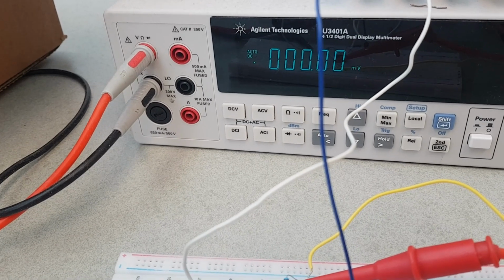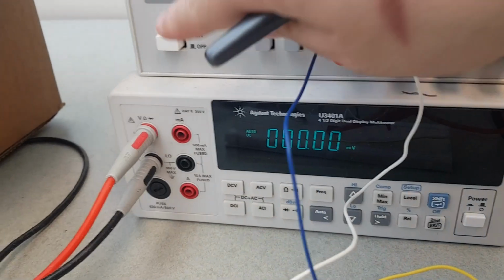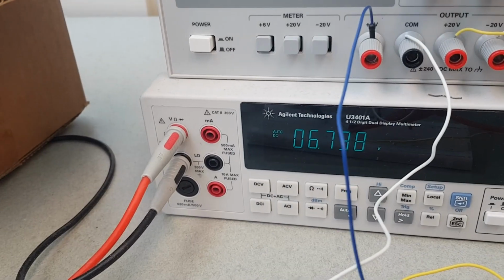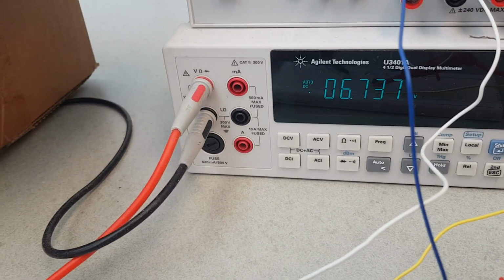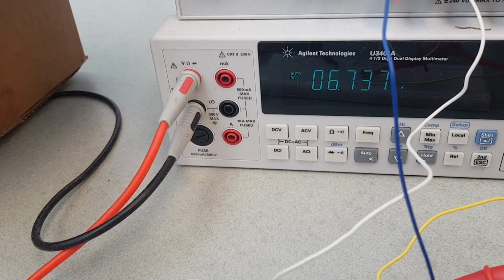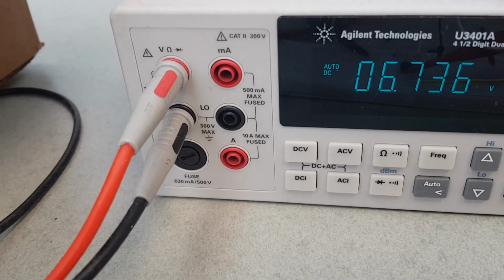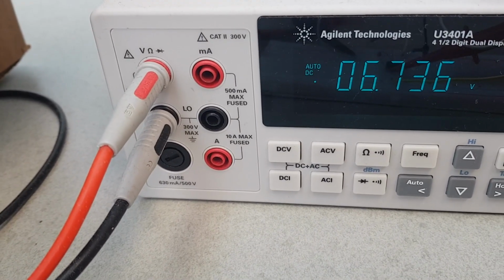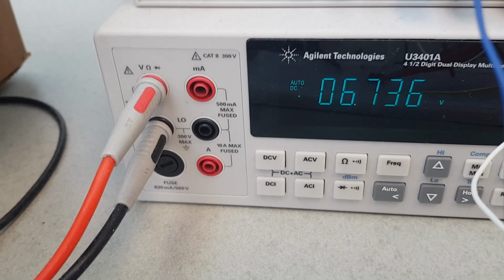Now let's start to measure the voltage, and this is your Vout. Of course, there is no voltage because there is no input. We have not connected the bias yet. Connect the bias here, and my input is 0.6, and we are expecting to get 6.6 volts, which is very close, 6.7. And notice here the sign of the output voltage is positive because this is a non-inverting amplifier.